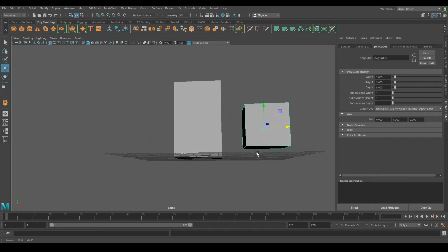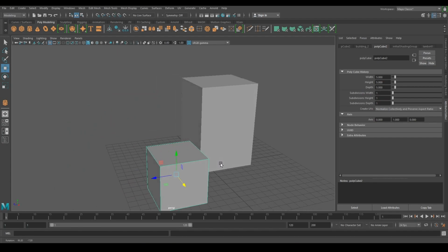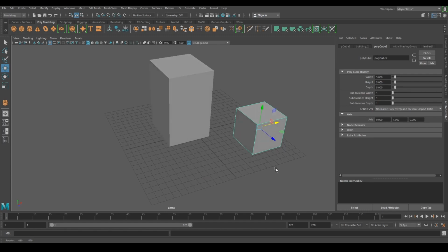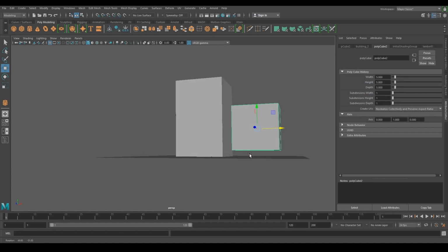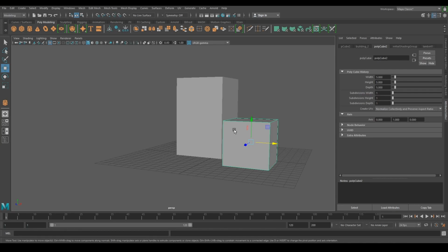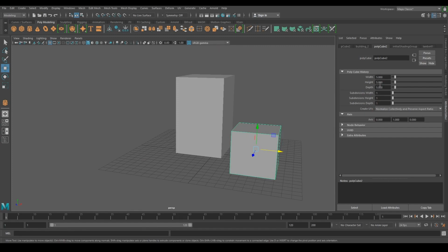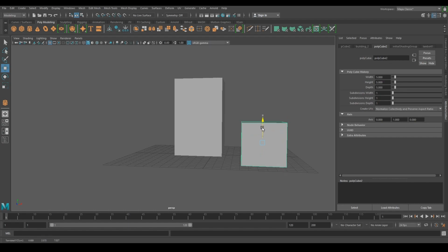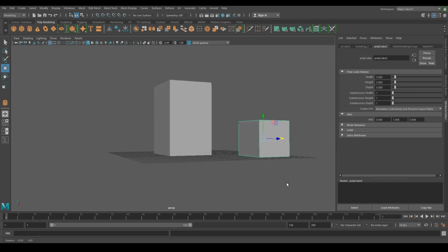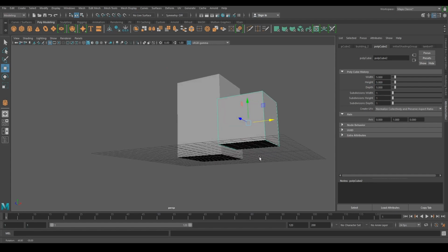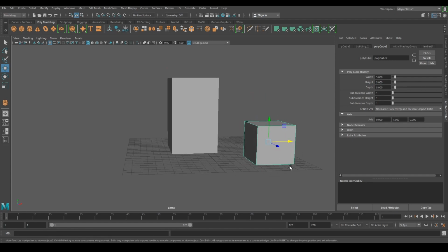I can rotate around that. You'll notice that because it's slightly smaller than the cube you originally created, it's now hovering, because the origin of the majority of the primitives is from the center. Because we've set width 5, height 5, depth 5, we want to move it. We could just move it and try to approximate where we wanted to put it, but we don't necessarily know exactly where it is, what particular height, or where it is relative to the 3D space.